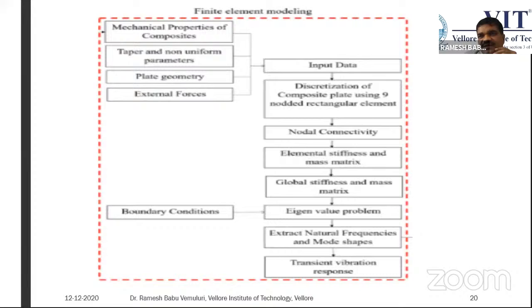Normally these 2D elements are for plane stress cases, and the plane strain condition is taken for thick objects where there is more thickness. In the thickness, normally we go for a three-dimensional object, or even a two-dimensional one also. So a three-dimensional element we can also consider.